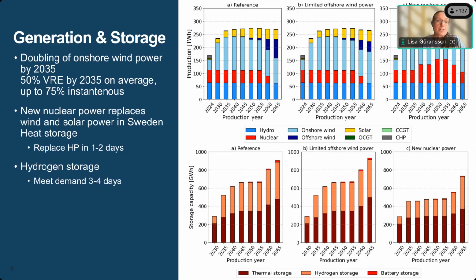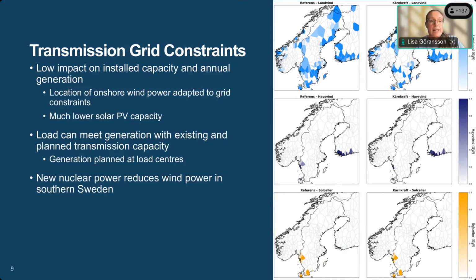And then if we look at the results from our other capacity expansion model with high geographical resolution, we can instead see the placement of these generation capacities across the Nordic system. Overall, we get very similar total system composition with our large-scale, rougher capacity expansion model and our detailed capacity expansion model. One difference that we see is that we get less solar PV investments with our high geographical resolution, because PV production is concentrated in a few hours of the day, and then we need a lot of capacity basically to transport it from one node to another.